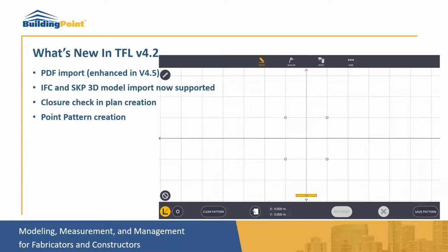It can contain 1 point, 2 points, 4 points. They can be aligned in any quadrants that you wish. You can input the X and Y values in the input form and then define your pattern. You save that pattern, and once it's saved, you then have the capability of inserting that point pattern to any point that is available in your map.